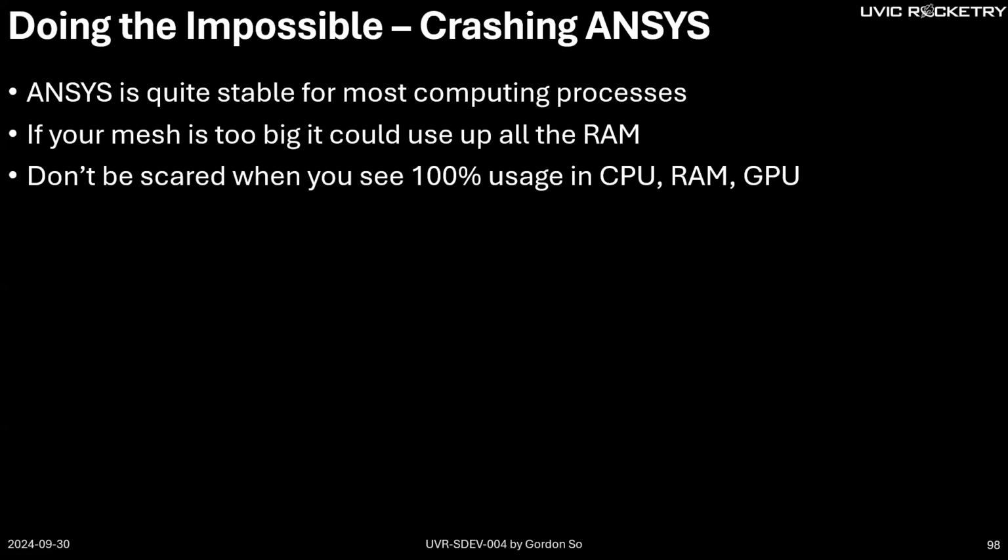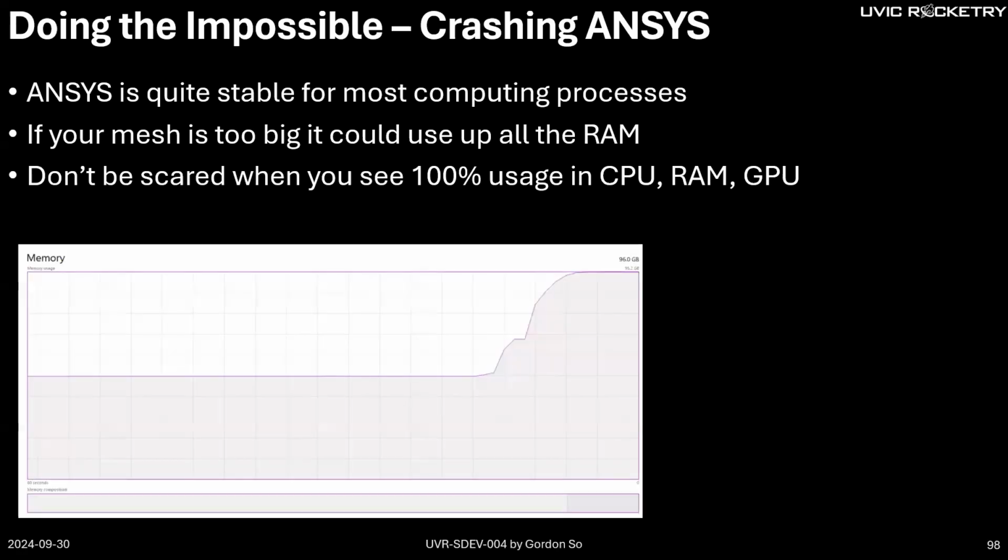If your mesh is too big or too fine, it actually uses all your RAM. Don't be scared if you see 100% usage. Look at the spec of this computer, 96 gigabytes of RAM. But if you try a really, really fine mesh, you can actually use all your RAM, which was pretty crazy to me when I got my computer.